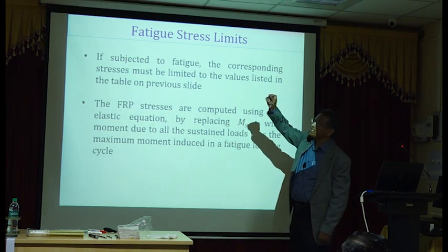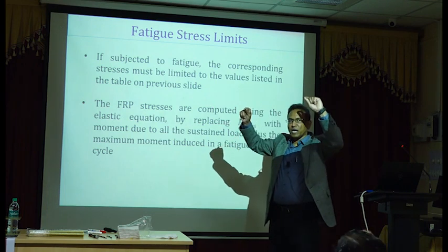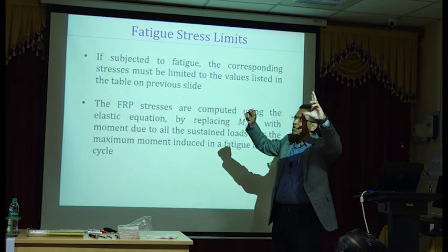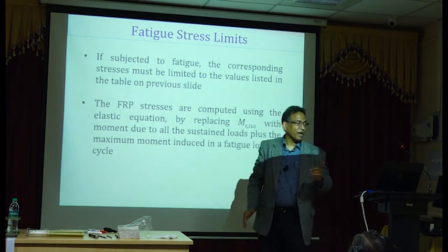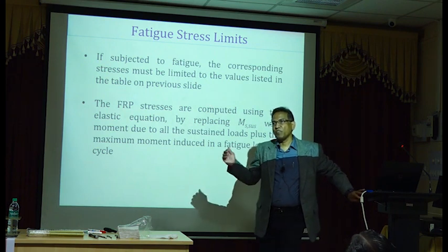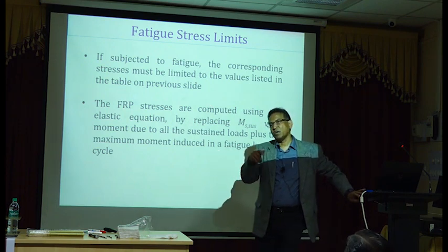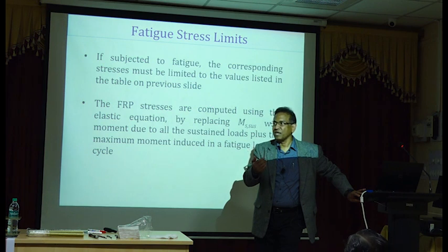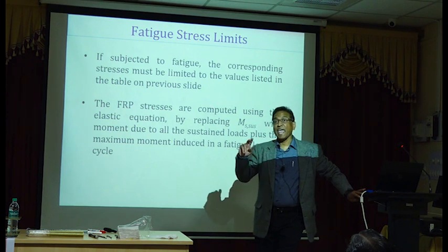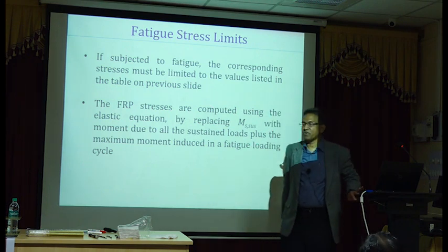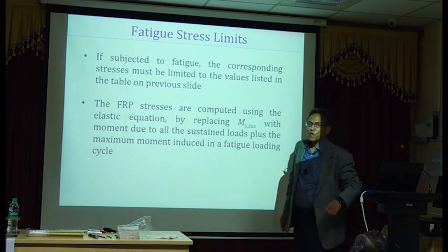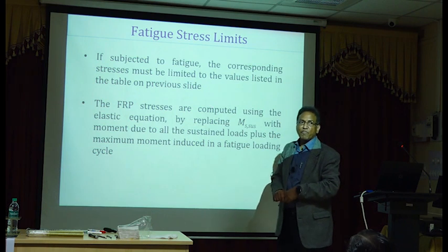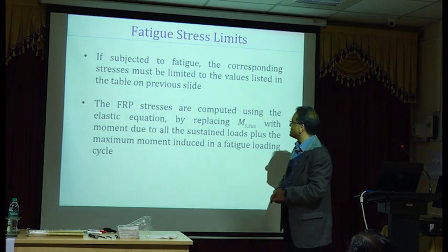And that maximum stress plus the stress due to sustained load, these two need to be combined. So this plus this will be compared with the 0.2 ffu limit for glass FRP or the 0.55 ffu limit for carbon. So that's what you will be doing if you have both sustained load effects and fatigue. Fatigue is a killer. It's very difficult to manage fatigue and creep rupture in FRP reinforced beams. Something to remember.